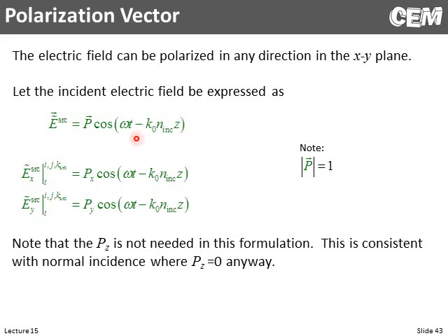And notice this is for normal incidence only. There's actually problems accounting for oblique incidence in finite difference time domain if you have periodic boundary conditions, and you also want to use a pulsed source. So most of the time, finite difference time domain just has a normal incident wave. If it's not periodic, or if any of those things are relaxed, we can get away with sending waves in at different angles. But there's our E sub x and E sub y source.